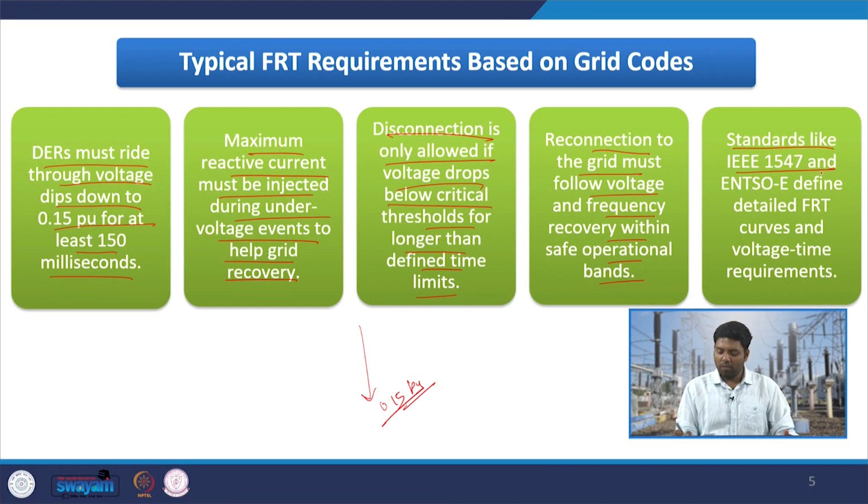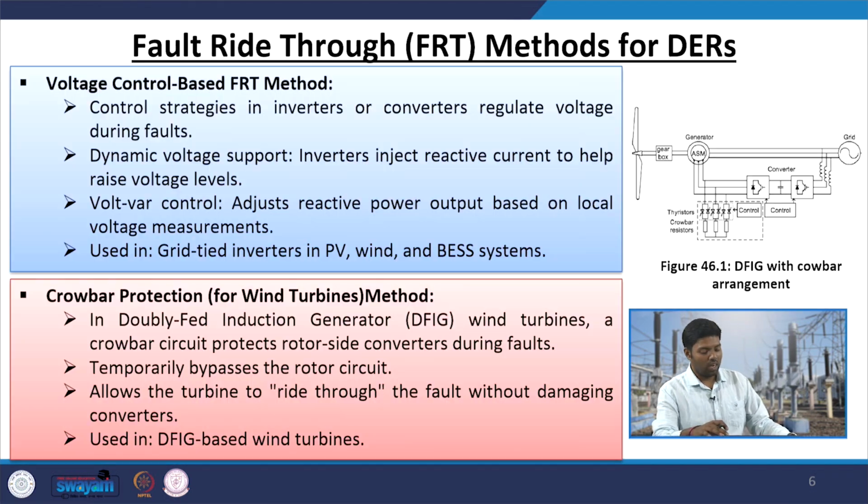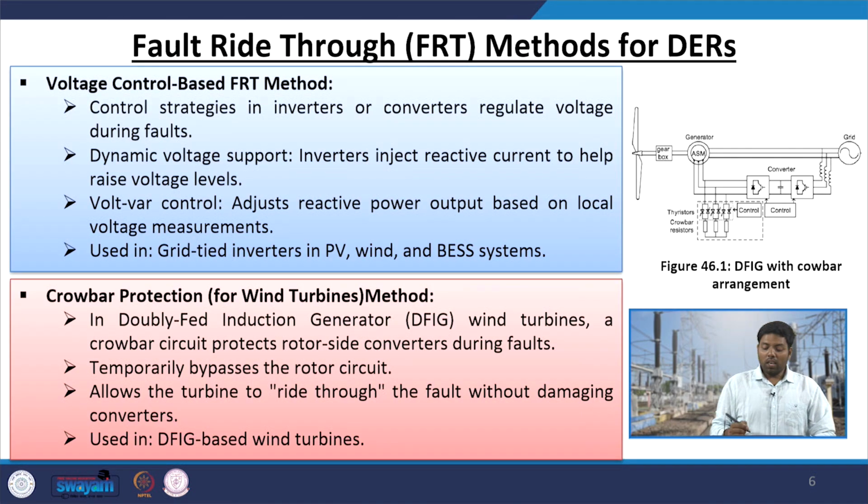Standards like IEEE 1547 or ENTSO-E define detailed FRT curves and voltage-time requirements. So, these standards are generally followed for carrying out the fault ride through analysis. So, what are the fault ride through methods for DERs? First, you can do the voltage control based FRT methods.